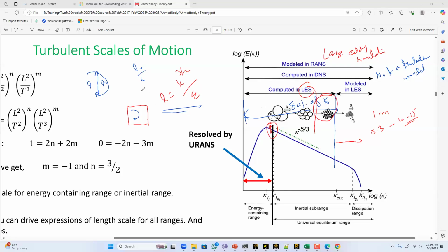In this case, we should make the mesh size smaller. For example, if I divide this cell into 4 parts, now this eddy is inside these 4 cells, and we can solve that eddy through the numerical methods. To make it very simple, what they are proposing is that you should divide your length scale by 6, and that should be your mesh size.